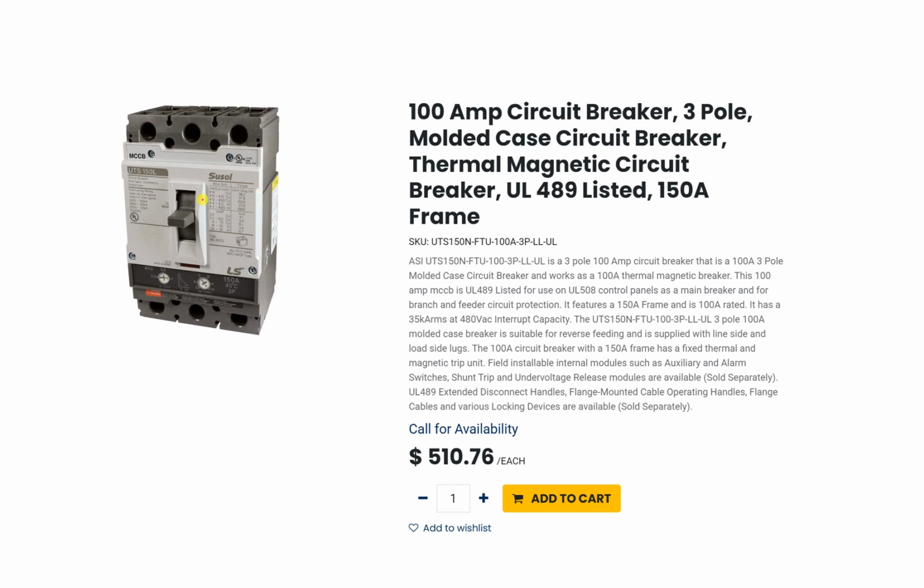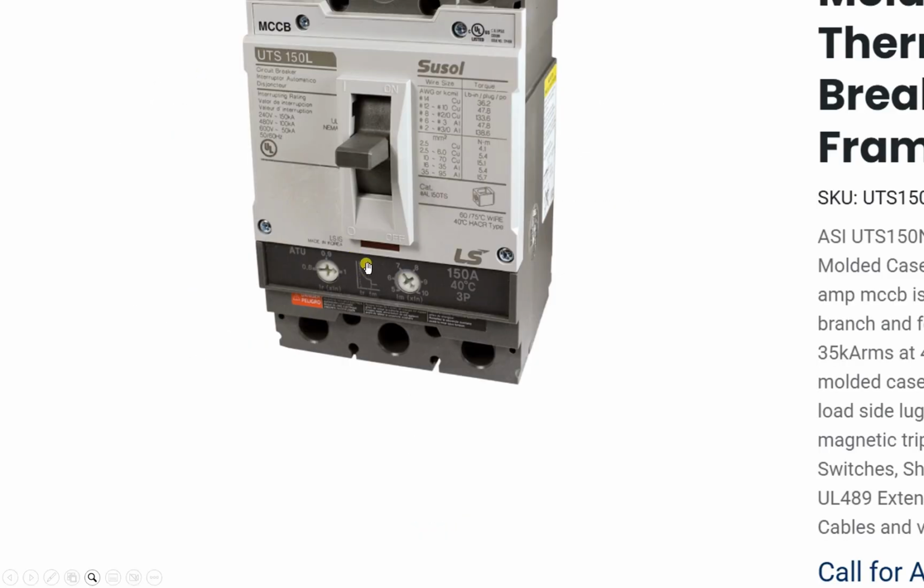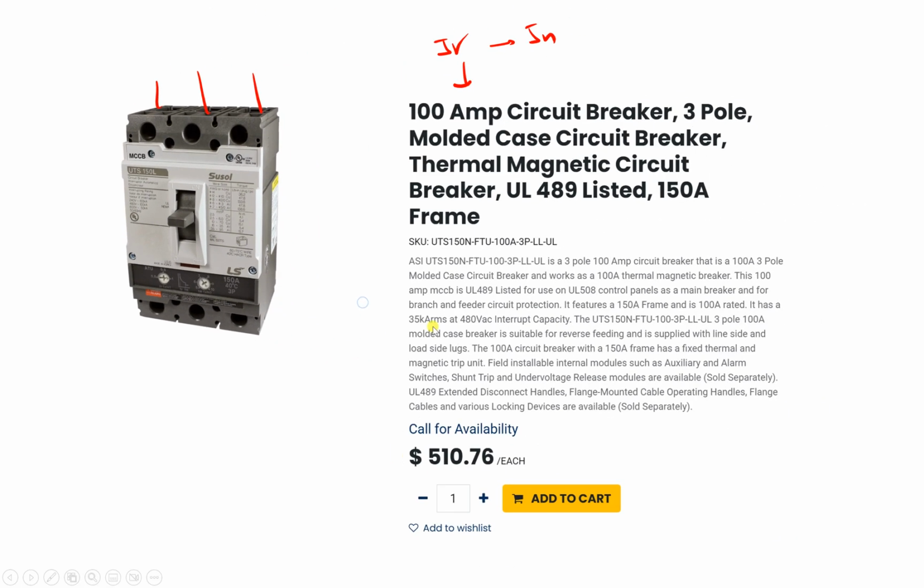Okay, so let's continue. This is a circuit breaker from the website of the manufacturer itself. You can see 100 ampere circuit breaker. This represents the rated current, or the nominal current IN. 3 poles means that it's for 3-phase, 1, 2, 3. Molded case circuit breaker. Thermal magnetic means that it has thermal protection. If we zoom in like this, you can see thermal protection, overload, and short circuit protection. UL, okay, this is the standard it follows. 150 ampere frame. You can see 150, this is the frame maximum. The ampere will reach up to 150 ampere for this model here.